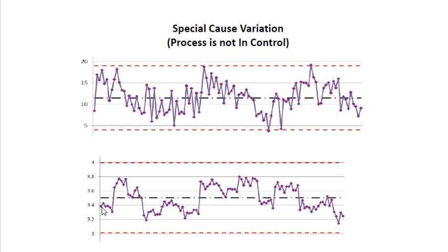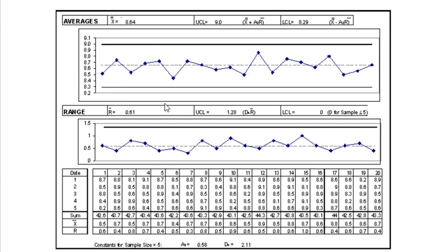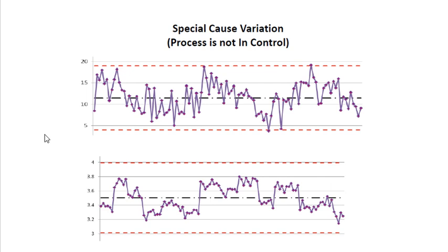It isn't like our normal pattern like you saw before. You can see how the data are so close to each other, and all of a sudden go up and down like that. Whereas in the normal process, look at this, they're far away from one point to another in a very consistent way. And of course, there is up and down, but not crazy like here. Here is pretty crazy. So it means that your process is not in control, okay? It doesn't have consistency. The patterns vary very drastically.